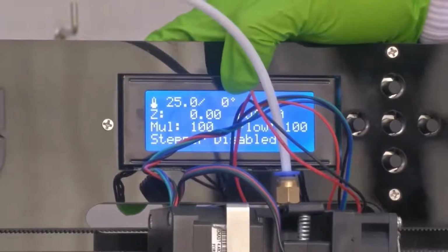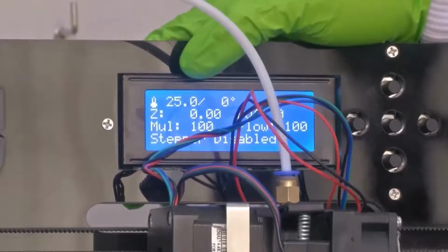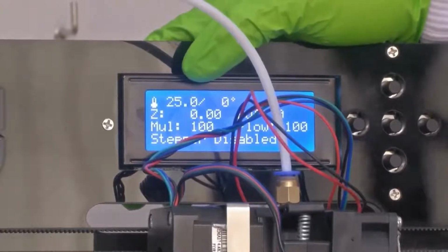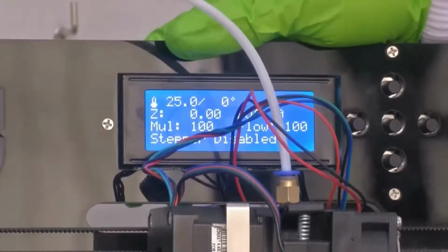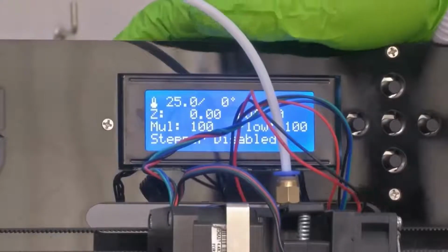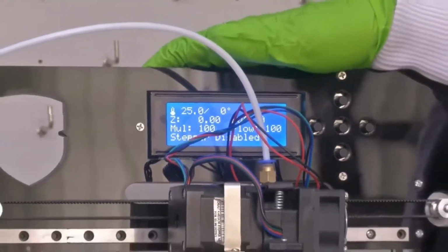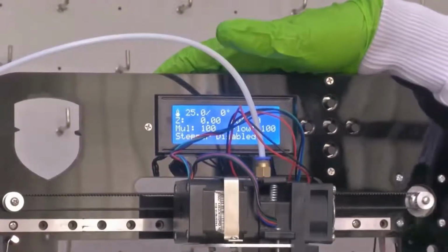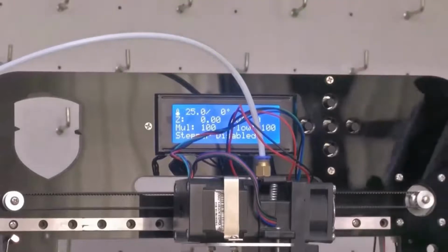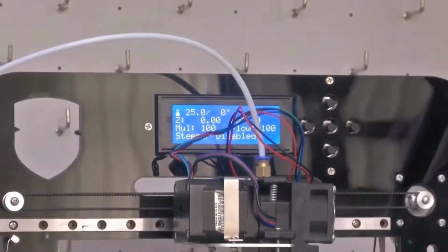Now how do we load the design and how do we make a design? Usually the designs are made in CAD using CAD software like Pro-E, SolidWorks, etc. The CAD files are then converted into another format called STL. STL stands for stereolithography. The .stl file is then converted to something that this machine can understand, that is called G code.